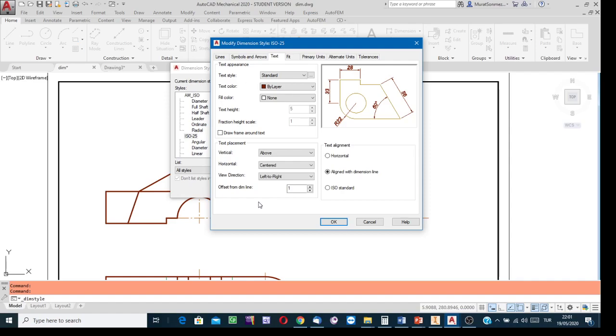Underlined dimension means that on the projection the size is wrong, but the dimension which has been shown is the correct dimension. To draw the attention of the reader to such a fault on the projection, it is a must. In such a case, underline the dimension. Okay.